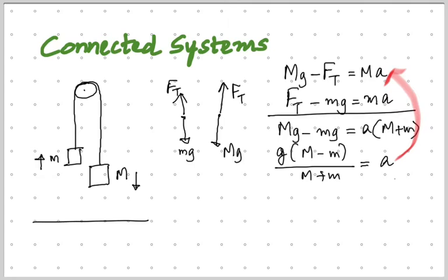The one reason why students struggle on this especially is because they try to memorize. So let's take memory out of the game and you be listening to me. You have to draw a free body diagram, which means you look at one object at one time. So you imagine the other one is absent. So let's look at this.